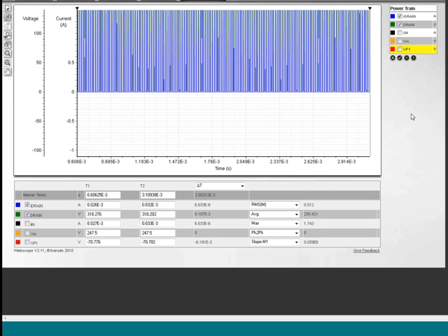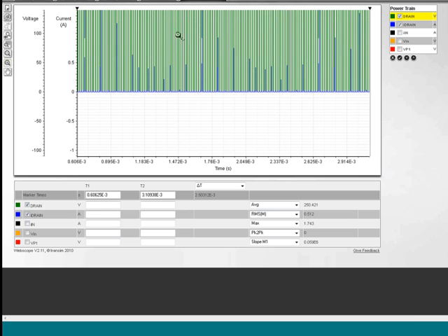There is one more feature that I do want to show you on this waveform viewer. You'll notice here that the drain current is on top and the drain voltage is under it, and it's somewhat hidden because of the number of blue waveforms. If I click on the drain current, I can move that up, and you can see that brings that to the top of the pile, and so my drain voltage is actually the one that's on the top. If I push it down, it's going to put this waveform on top, this waveform next, this waveform next, this waveform next, this waveform next. So there's quite a bit of capabilities in the waveform viewer.